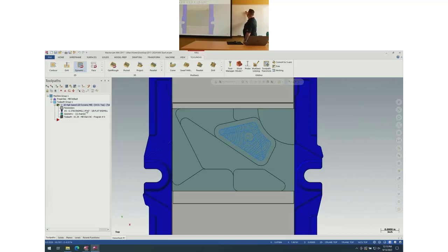The problem is that the diameter of the tool is .375, but the helix that Mastercam gives us by default is 1/4 inch. That means that by the time it's done spinning around, there's actually a post in the middle of that helix. And that kills tools really quickly.